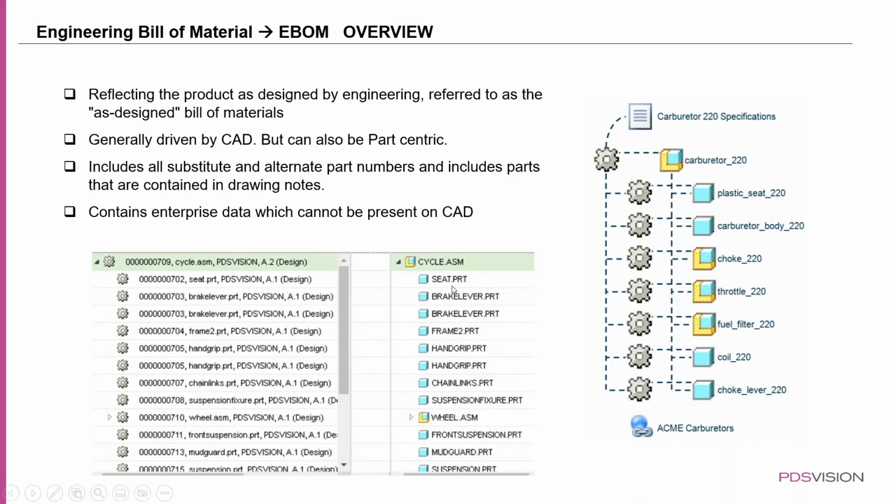So if I am trying to save or check in, check-in is usually getting the CAD inside Windchill, right? So when we try to check in a particular CAD assembly, for every model inside that CAD, we can associate a WT part inside Windchill for it.